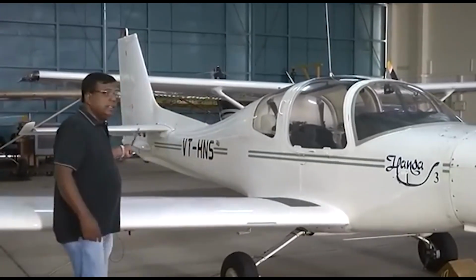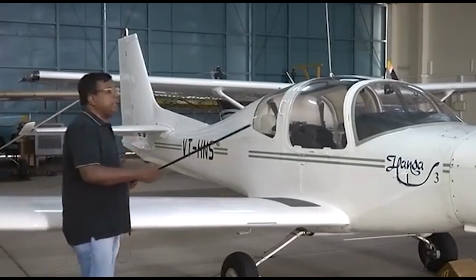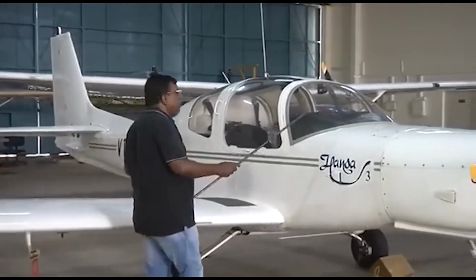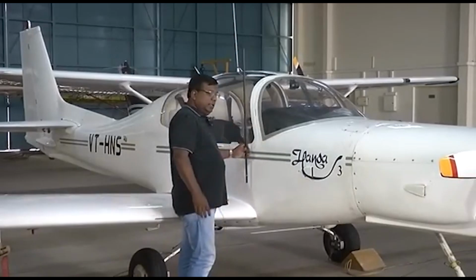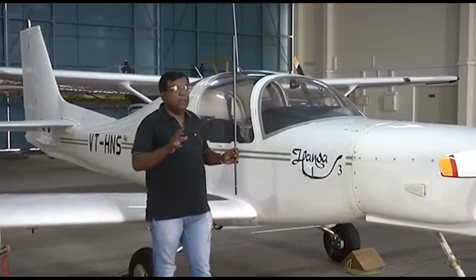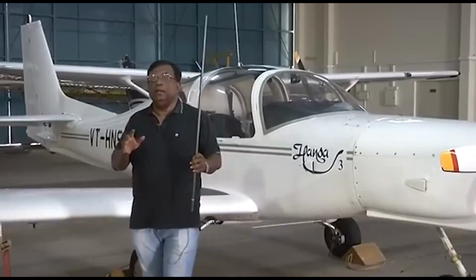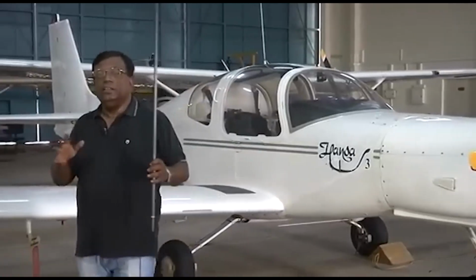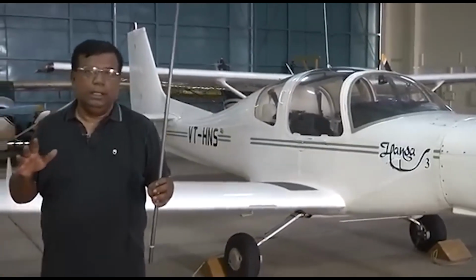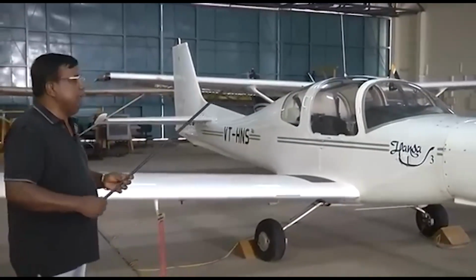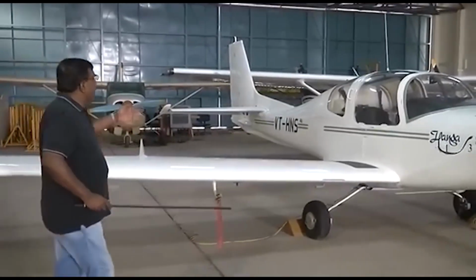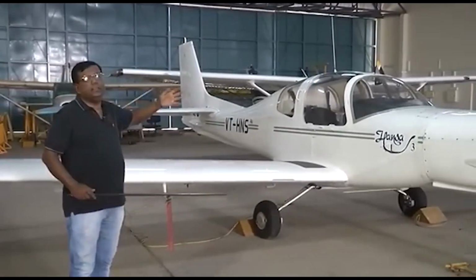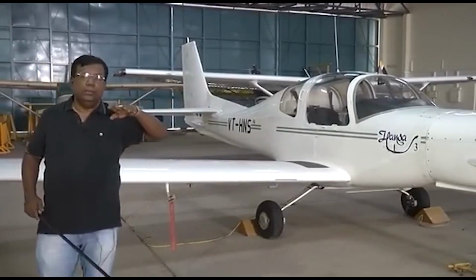Similarly, from the horizontal tail, all those forces which were acting at different points of location, I am transferring them to CG with force and moment. So now, when I apply the point mass model, I have an assumption that all these moments are balanced. And in practice, how are they balanced? They are balanced by design, by a configuration design. And in addition, you can use elevator, trimmer, etc., to make sure all those moments are balanced.